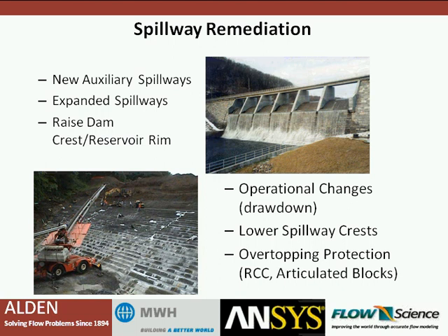The photo on the upper right, we've added some spillway capacity to the center of what used to be a solid gravity dam. And on the lower left, we have an overtopping protection project where we've actually armored the earth embankment with some roller compacted concrete. Anytime we talk about making these kinds of physical changes to a project, though, we're talking about quite a bit of money for the owner. And that's where CFD can play a very important role in helping us to optimize the use of these resources and getting the most cost-effective project for the owner.